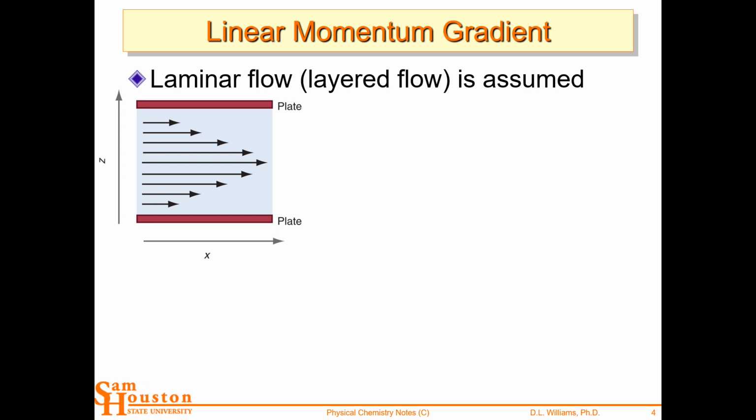That word laminar is kind of a strange spelling, but if you think about a countertop, you have a lamination or laminate top that's layers. And so think of this flow as layers, kind of like a countertop with multiple layers, only it's a velocity gradient. So the layer that's touching the wall of the container is not moving. Otherwise, the container would be moving. So the container's still and the fluid is flowing. And so it has to go from stationary in contact with the container wall to flowing above that surface in some distance. Okay. So that's the gradient that we're talking about.